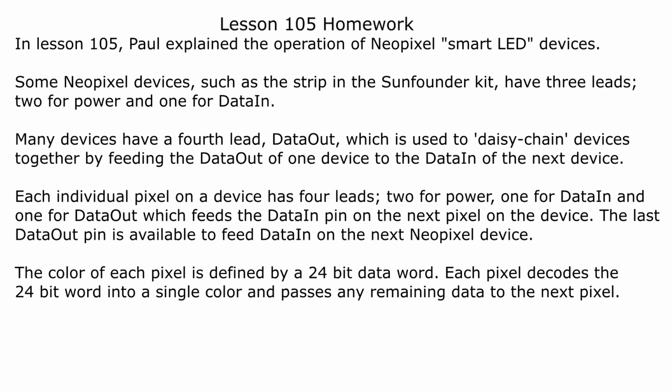Lesson 105, Paul explained the operation of NeoPixel smart LED devices. Some NeoPixel devices, such as the strip in the SunFounder kit, have 3 leads, 2 for power and 1 for data in. Many devices have a 4th lead, data out, which is used to daisy chain devices together by feeding the data out of one device to the data in of the next device.